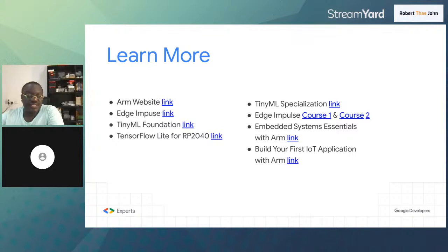The frame rate is not the best. What that means is that it's not going to be doing it at 30 frames per second. But you can run it. Anything that has a Cortex M4 and above will do that for you. The bigger consideration is what sort of camera you have that is going to take the image and do the processing. Of course, the Raspberry Pi 4 will process at a much faster rate.